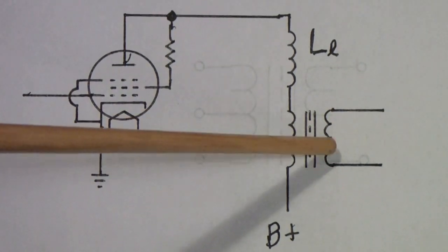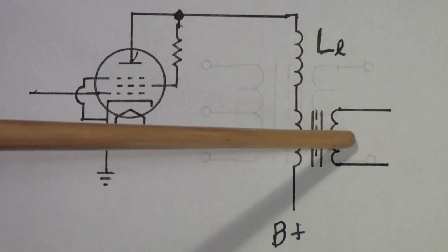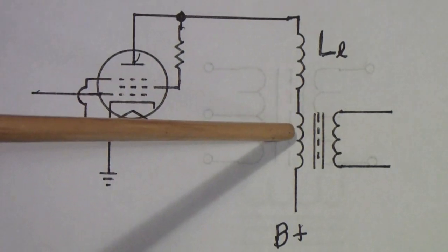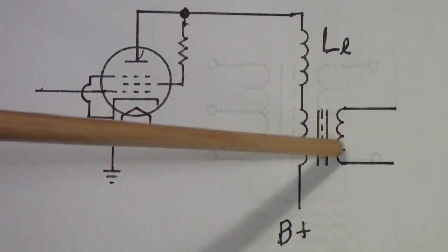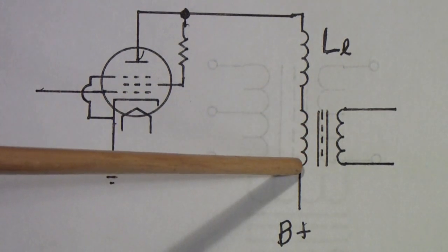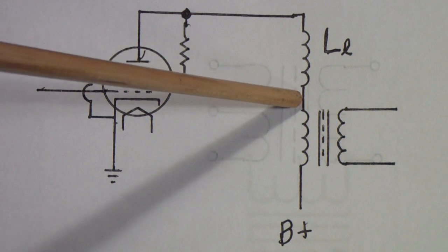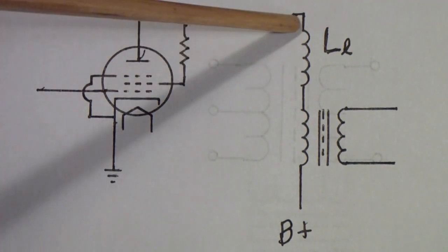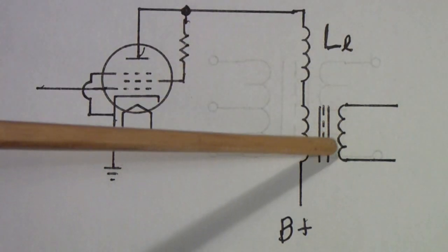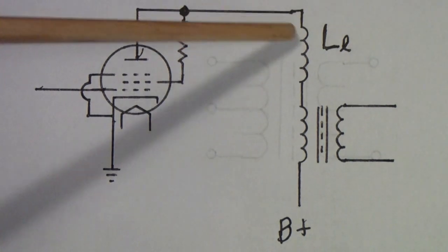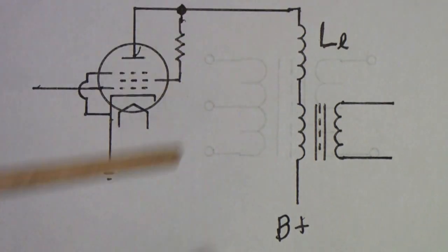This is a damping factor, which we haven't talked about, but it's an important characteristic of amplifiers. But because not all of the flux from the primary makes it to the secondary, some of that collapsing magnetic field produces a reverse EMF, that is a reverse voltage. And we model that by putting this inductor in series. This inductor is not magnetically coupled to this transformer. It is a fiction that we are using to create a model. And this is where leakage inductance comes from.